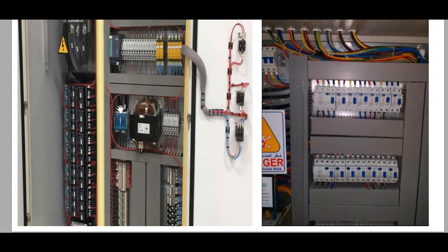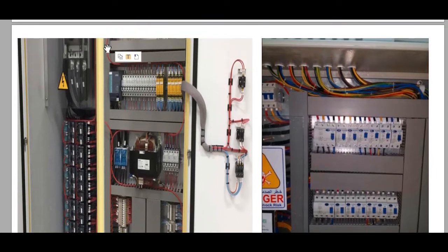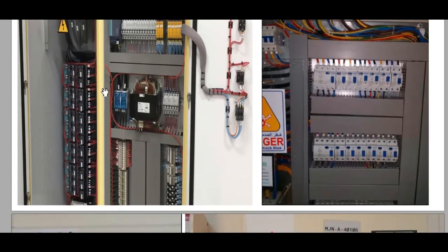And it must also be with all. You see here there is a tag, there is a numbering, everything okay. Here we have a danger sign, very nice. Here is very nice wiring, but you see this wire is not allowed, and this wire is not allowed. This wire is not allowed, and this wire also is not allowed. As you see, these wires come over the cable tray, so this must be rejected.